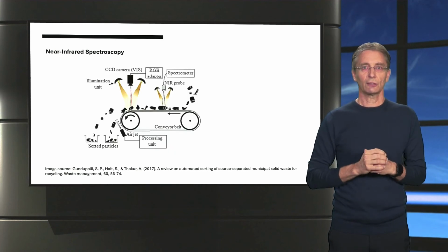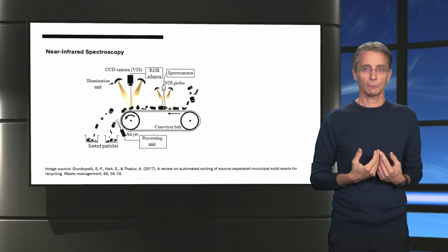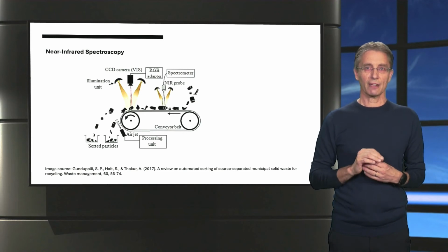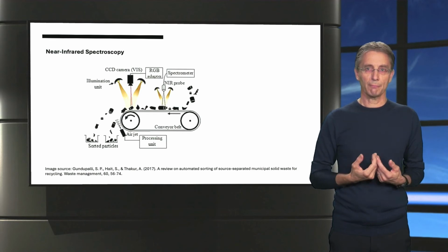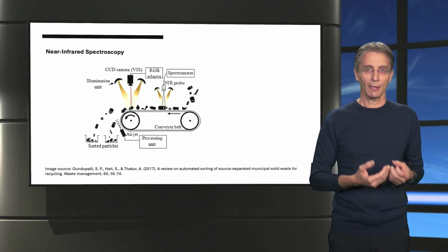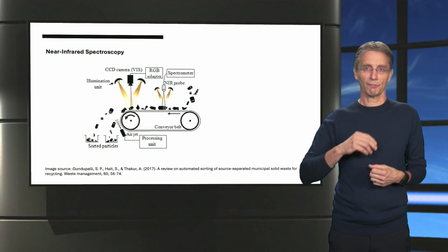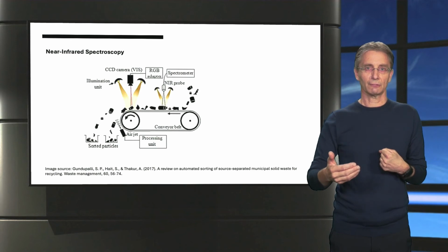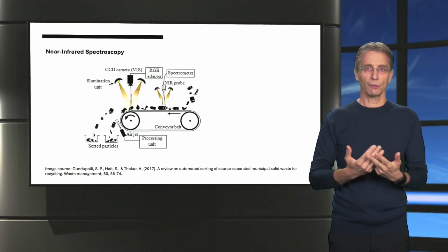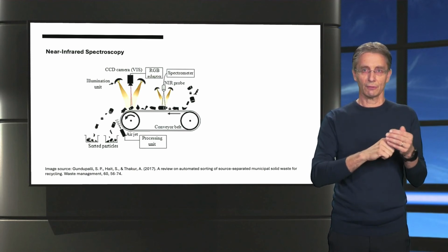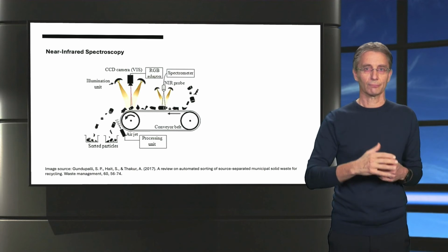There are also technologies that use optical instrumentation to sort streams of mixed polymer particles. A commonly used method is near-infrared spectroscopy. It is a relatively fast method that doesn't require surface pre-treatment of the particles. It is based on differences in absorption of near-infrared light by different polymers. After the plastic particles are illuminated, a near-infrared sensor detects the reflected wavelengths. With this information, a processor unit determines the polymer type and sends a signal to an air jet, which blows the different polymers into separate containers.